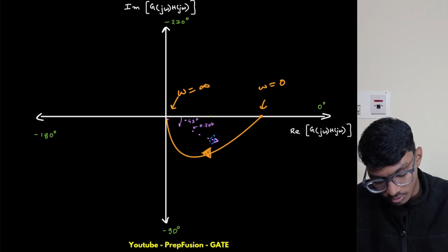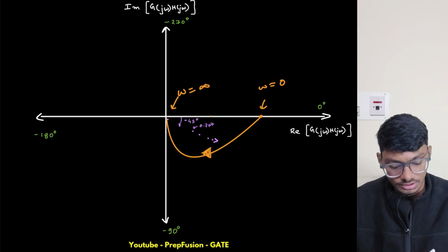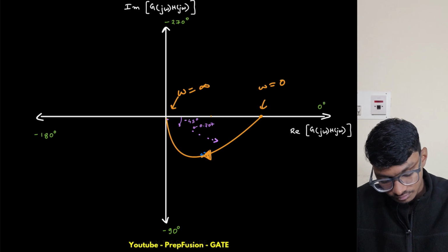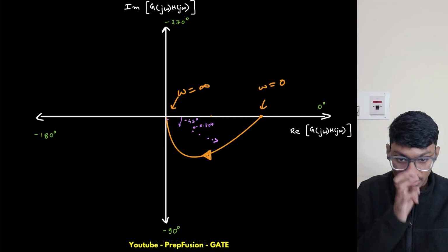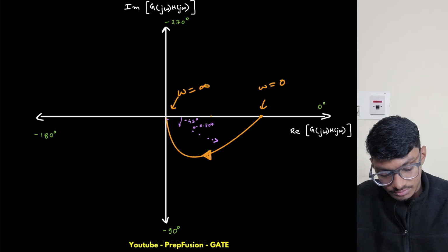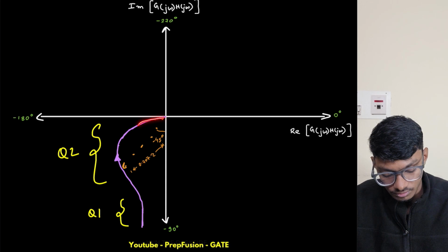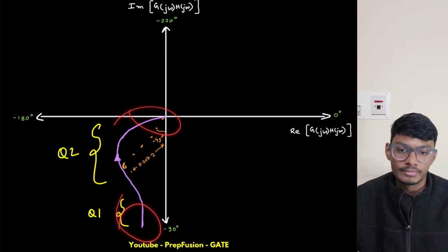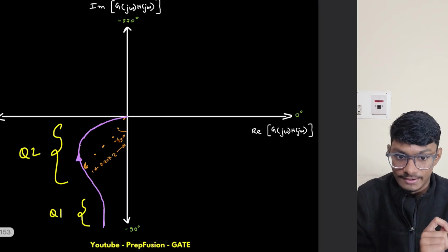You guys check. Plot the imaginary and the real, and from there, if it follows the locus diagram of a circle, then it will be a circle. But I don't think this will be a circle. So this will follow like this one. I hope you get it. So this is ending towards minus 90, not 0 degree. So yeah, this is minus 90, and I am further shifting the head by 90 degrees. Both the head and the tail are shifted by 90 degrees in the clockwise direction if a pole at the origin is added.